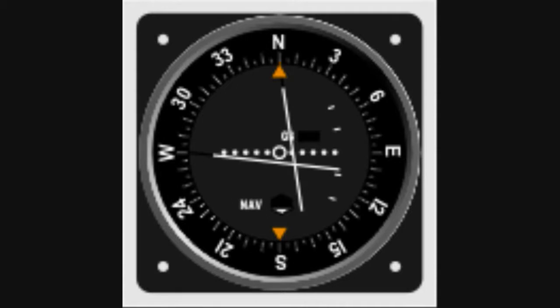So if this was a real landing, we would lower the nose a bit. We'd push forward on the stick. As you can see, we're a little bit to the left because the needle is deflected to the right. So we'd correct right a bit. We'd give a little bit of right aileron. So, with this in mind, we can use this to have what is called a precision landing, which means that you can get right on there.